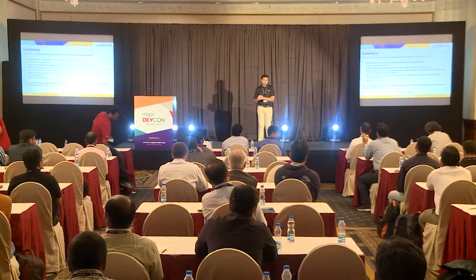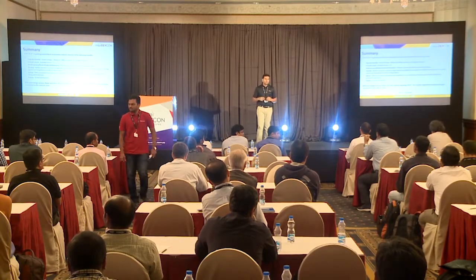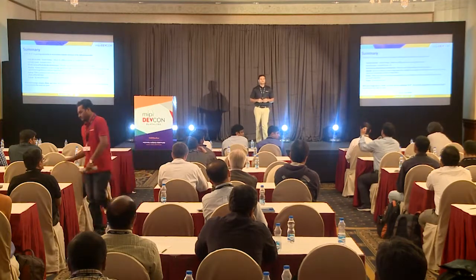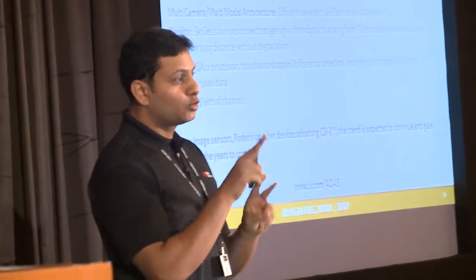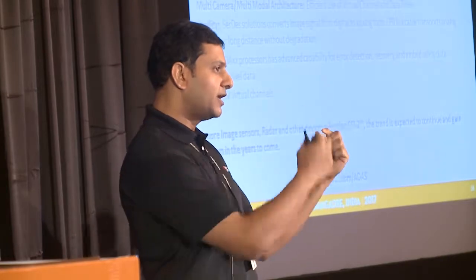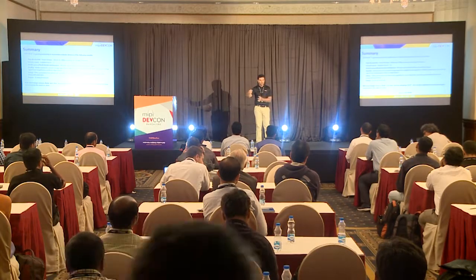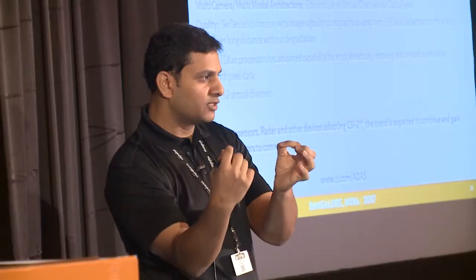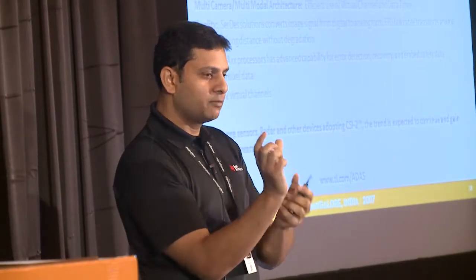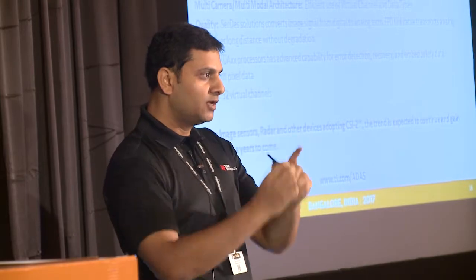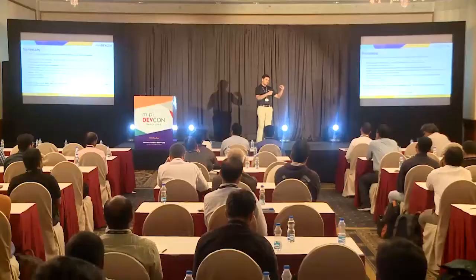What I'm trying to understand is where is the CSI link? The CSI link is not between the camera and the ADAS chip, right? So the CSI link is in 2 places. There is the camera and serializer, which are on the same board, connected by a long FPD link cable to the deserializer and the vision processor, which are on the same board. So there is a CSI link between the deserializer board and the processor, and there is another CSI link between the camera and the serializer.